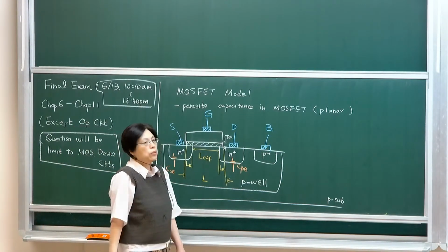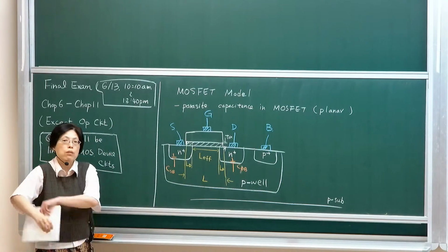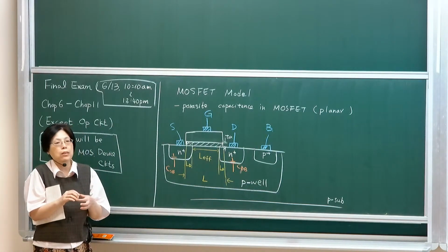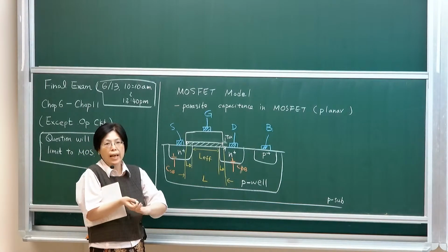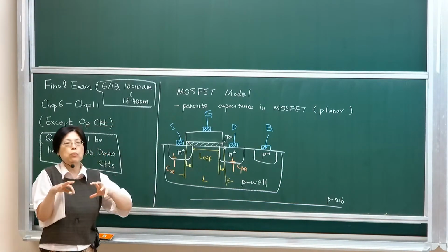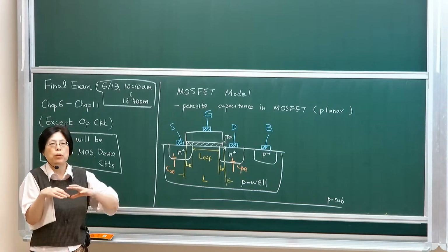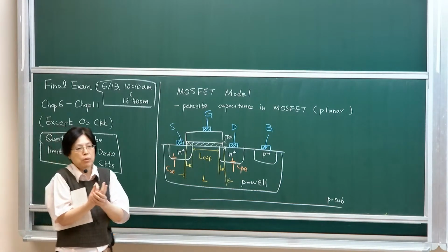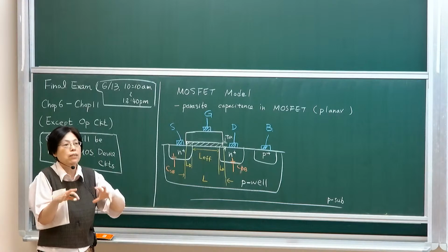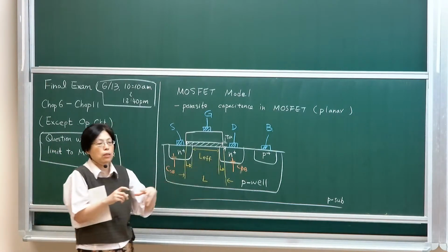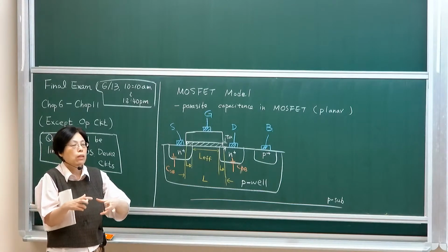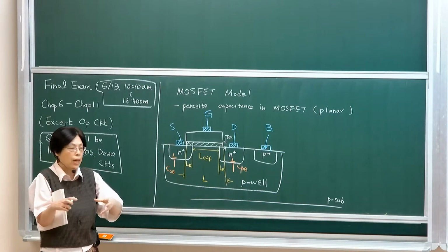Of course, if you want to find out the real capacitance, if you ever did SPICE simulation nowadays, there is something called post-layout simulation. If you do a pre-sim simulation, meaning that you don't actually have the layout, then it's very hard to extract these parasitic capacitance because it would depend on the size of your transistors or size of your layout.